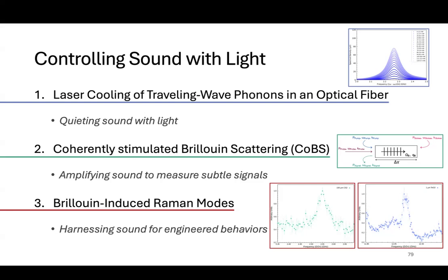So if you turn those powers down, you can turn it down so that there's no spectra and you're just seeing noise, of course, right? So for an SNR of about 5, I show that the instrument has a sensitivity of sub 10 femtowatts. So the scattered power that we are able to recognize with this instrument as a measurement at 5 SNR is sub 10 femtowatts, really closer to 5. 10 is conservative. Joel, could you repeat the question? Oh, yes. The question was, what SNR are we achieving with this instrument? Ultimately, what sensitivity, what performance metric from this instrument are we able to achieve? Excellent question.